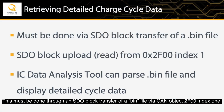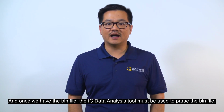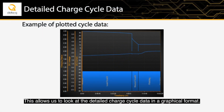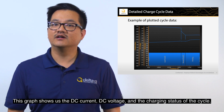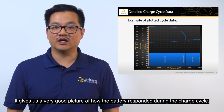This must be done through an SDO block transfer of the bin file via CAN object 2F00 index 1. Once we have the bin file, the IC data analysis tool must be used to parse the bin file. This allows us to look at the detailed charge cycle data in a graphical format. This graphic shows us the DC current, DC voltage, and the charging status of the cycle. It gives us a very good picture of how the battery responds during the charge cycle.